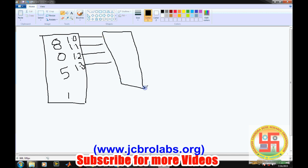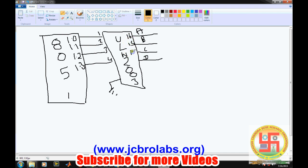As we have just discussed, ULN2003 is used to interface this unipolar motor. This is ground, and these are pin number 1, 2, 3 and 4 of ULN2003. Then there are 4 output pins of this ULN2003, A, B, C and then D. These are pin numbers 16, 15, 14 and 13, and these connect to the windings of the stepper motor.